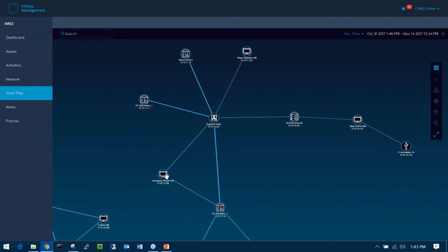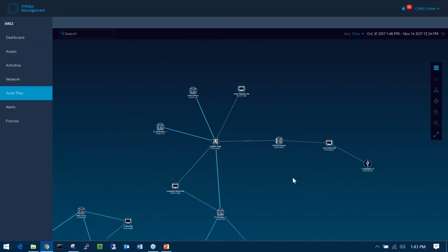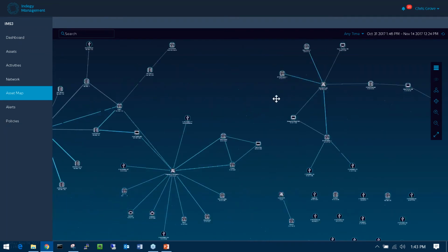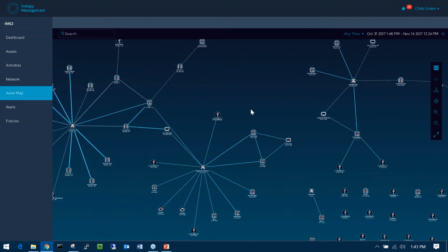He's talking to an HMI, and also the HMI and the engineering workstation talk to this particular PLC, etc. And I would expect to see in my environment 3 isolated air-gapped environments that are all doing their own industrial activities. So right away, there's my first network anomaly that I've identified: there's a connection between these 2 networks that I need to investigate.